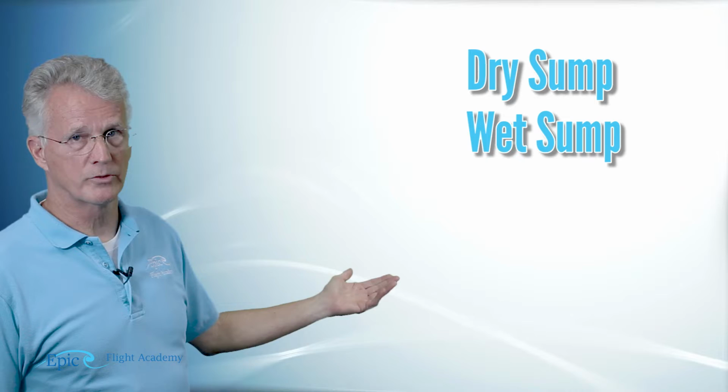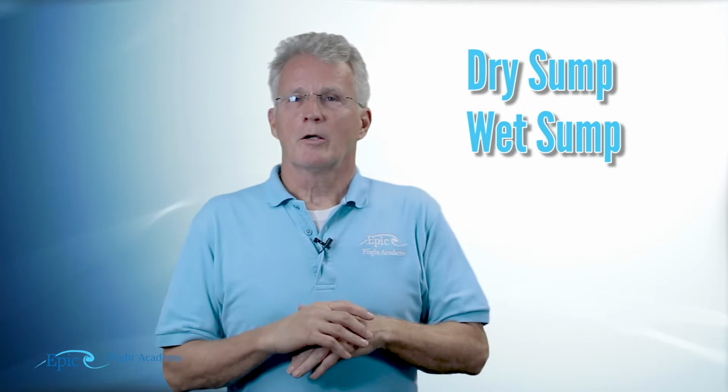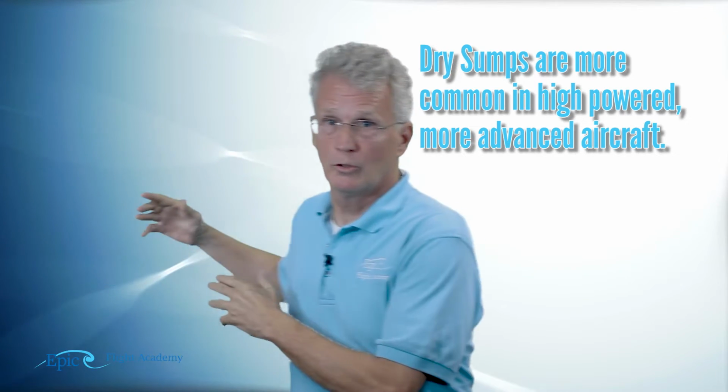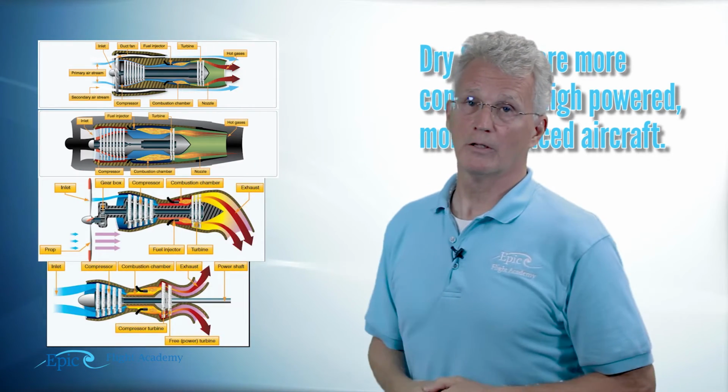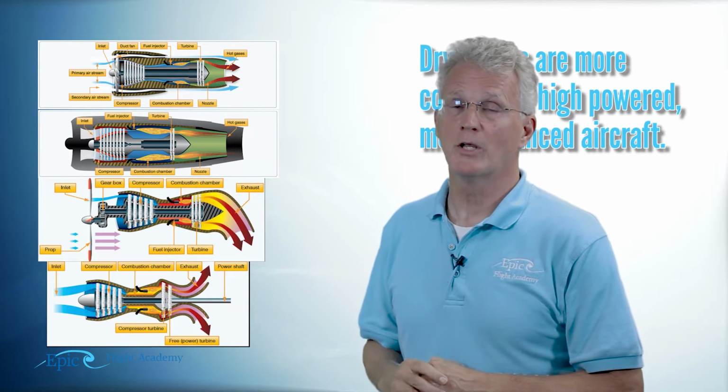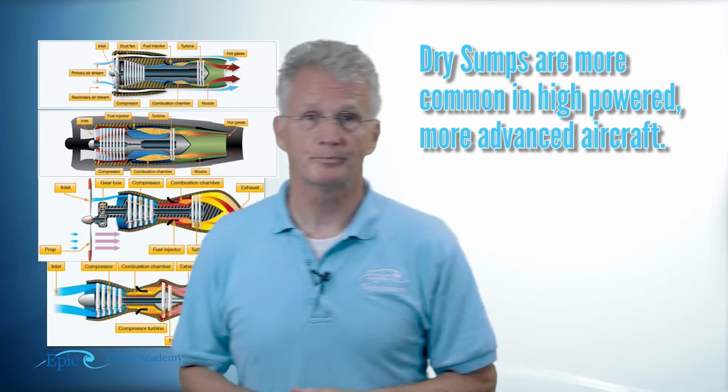When we look at oil systems in aircraft, we divide them broadly into 2 categories. We refer to these as dry sump and wet sump. We're going to talk much less about dry sump systems. Dry sump systems are more common in advanced high power engines and in turbine engines. In an earlier video, we talked about the 4 types of turbines. Turbine engines have dry sump systems.